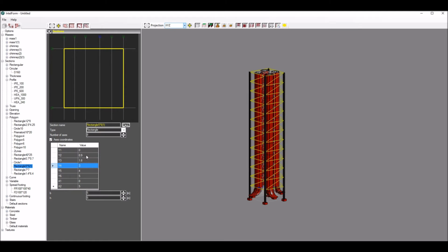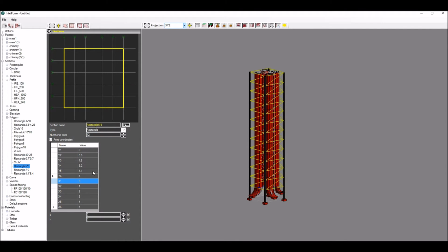We can define X or Y axes in any point and adjust their positions. To choose axis direction, one should click on any axis endpoint. If now I increase number of axes, program will add them in the same direction after selected axis. When axes are generated, we can define internal lines simply by clicking intersection points. Such internal lines can be later parameterized as contour lines.